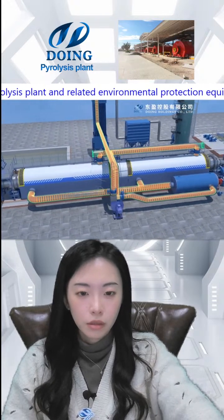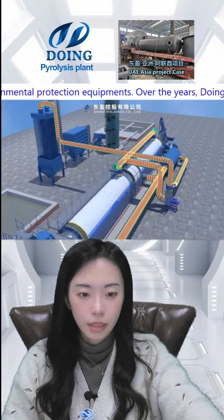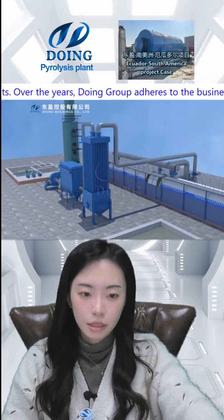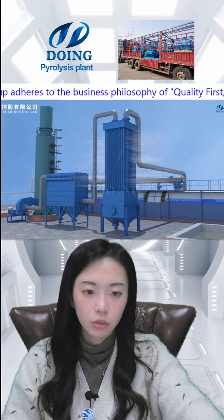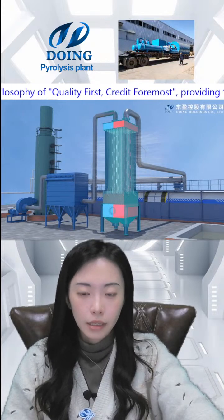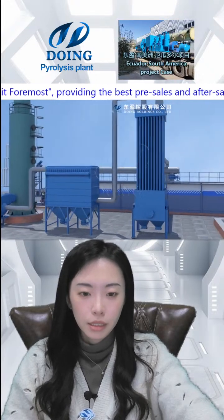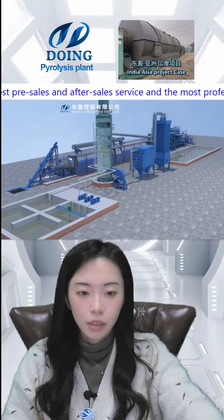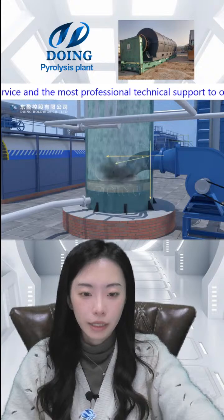And then for the purification system, we have 3 devices. The first one is the flue gas cooling system, an air-cooled cooling device. We also have a water-cooled one. This air-cooled one will lower the temperature of the flue gas. The second is a post-dust collector to remove the dust. And the third is the glass fiber reinforced plastic desulfurization tower. The flue gas has been cooled to below 120 degrees when entering this part.